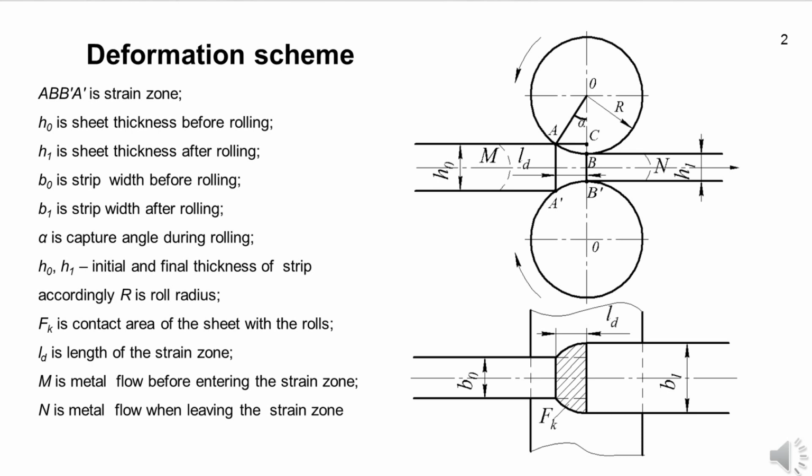Cold rolling produces strengthening, grinding and elongation of ferrite grains along the rolling direction. The total compression during cold rolling determines the final texture of the deformed material. A high degree of cold deformation produces fine grains.